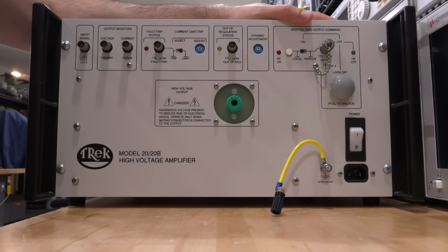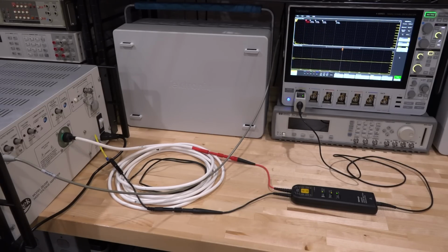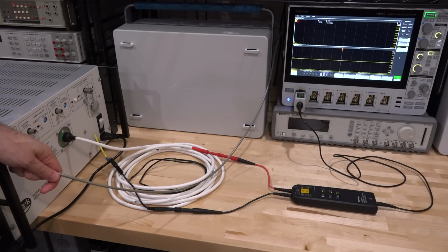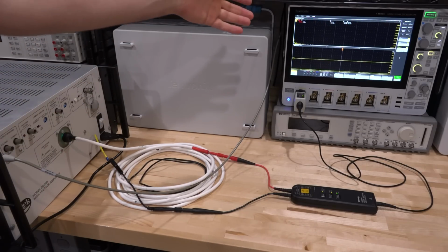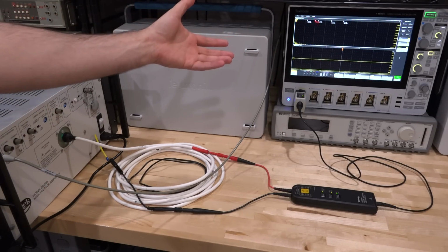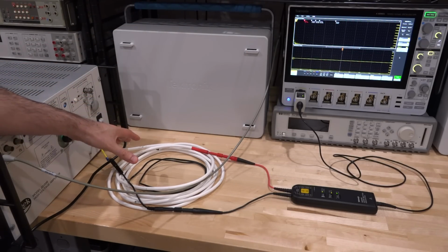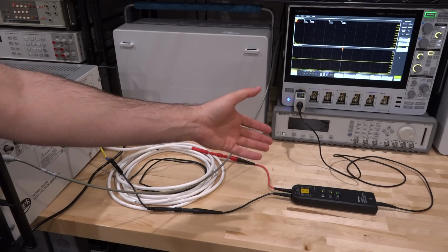Nonetheless, we're going to do some experiment with it, this time a bit more carefully. So let's measure some high voltage waveforms coming out of the amplifier. The setup is pretty simple. I have the input connected to the arbitrary function generator of the Tektronix 4 series, because these oscilloscopes all have a built-in AFG essentially, so we can use it to drive this. And then the output of that going through the high voltage cable is going through a Tektronix high voltage probe.